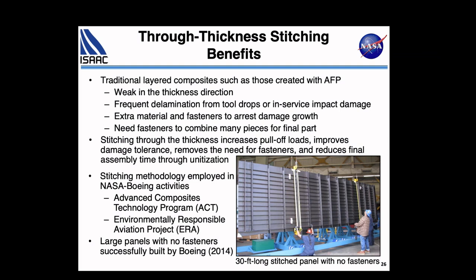And so there is through thickness stitching, where we use Vectran threads to combine your stiffener to your skin. You can stitch around the edges where you might be subjected to damage from runway stones, hailstones, tool drops, even carts running into the airplane. All of those are real world situations that will cause damage to your part.